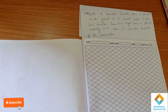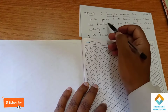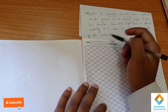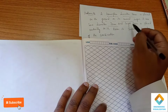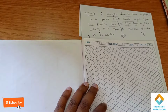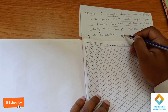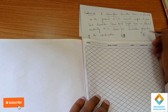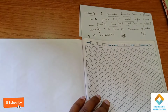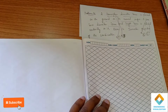We do another problem in ISO. In this problem, a hemisphere of diameter 70 is placed on the ground on its curved surface. A cone of base diameter 70 and height 70 is placed centrally on it. First we need to construct the hemisphere, second we have to construct the cone. So how do we do that?